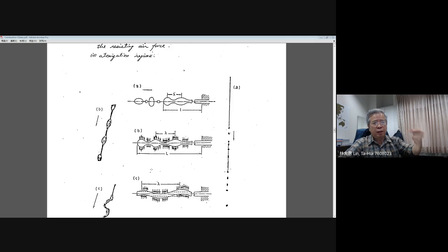They have a velocity difference, which gives a shear force, or what we call the aerodynamic resistance, on the surface of a liquid jet. The second one is the so-called surface tension, which tries to give the liquid the minimal surface energy to retain its stable form. Surface tension is one of the important forces acting against the aerodynamic resistance.